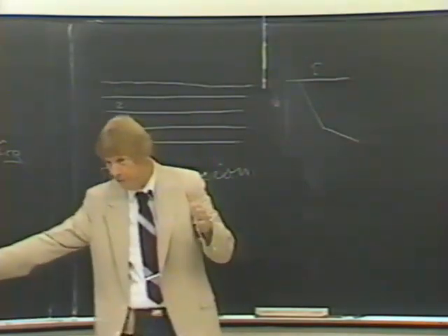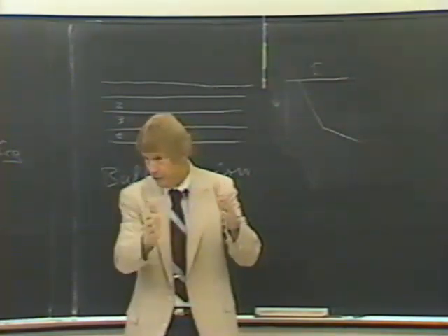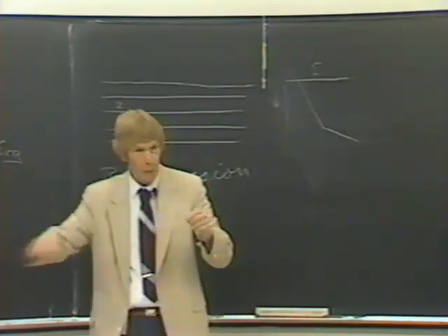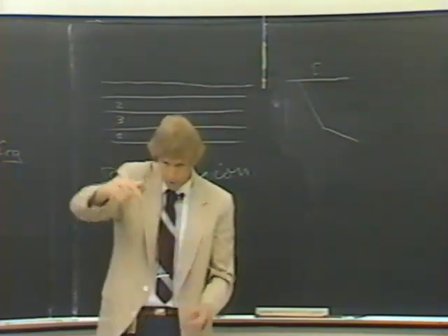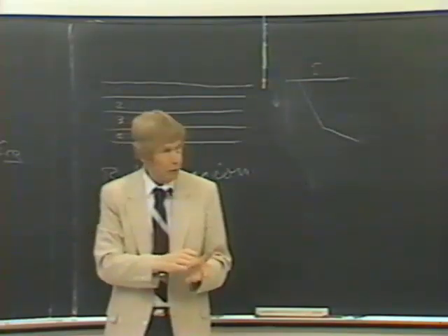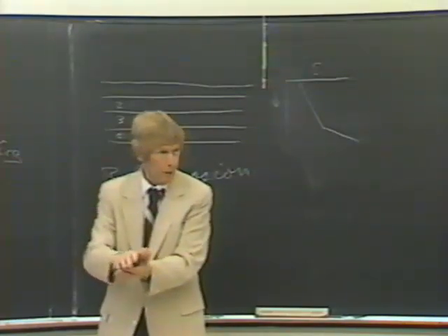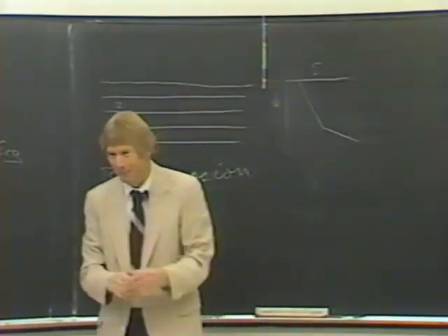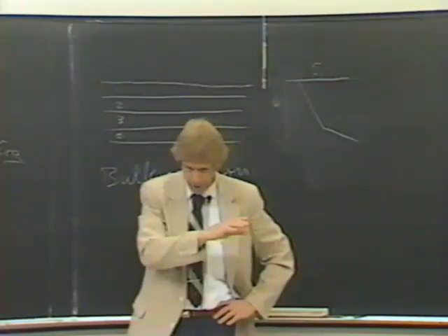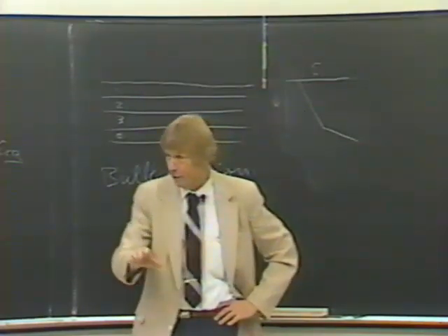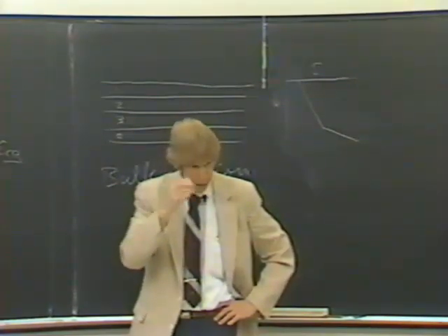And we used automatic cameras to measure the shape of the progressing front as it went down the channel. And we had markers, scales on the side of the flume and markers in the top. And there's a camera above and 2 cameras from the side. And from those you could get the speed and the depth of the advancing front. It took about 4 seconds for the mud to slosh down to the far end. It made a mess. But it gave you simultaneously the shape and the velocity of the advancing front. And then we used a one-dimensional model to model that with a simplified Bingham